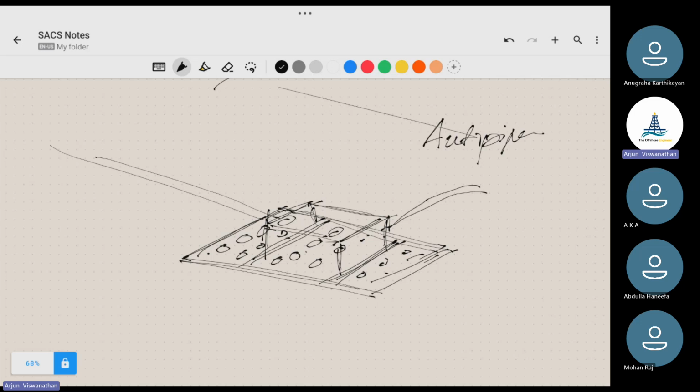There is one more component in these subsea structures, something called a skirt plate. These are just plates. They will ensure that our structure penetrates into the seabed. That will make sure that if currents pass, the structure will not be swept over, and it will stay in place during any external load acting on it.